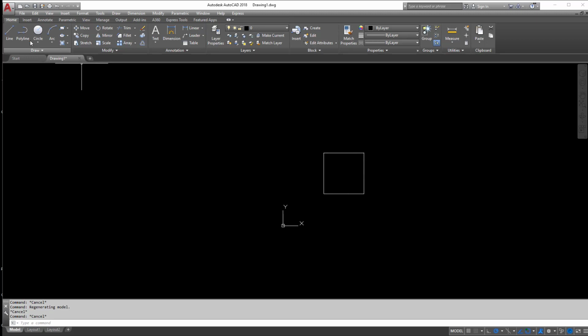And if you noticed, when I was drawing, it was automatically locking me in on these positions here. It is every 90 degrees. You see this green line. That's called polar tracking. So let's say I wanted to lock every 45 degrees instead of every 90. So down here at the very bottom, it's hard to see sometimes. In the bottom right hand corner, you'll notice this little circle with the angle symbol in there, and you'll hover over it and it'll say polar tracking, clear as day. If you click the little down arrow though, you can set what angles you want it to lock at.